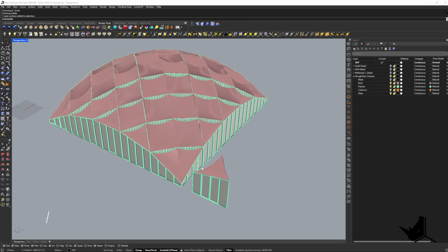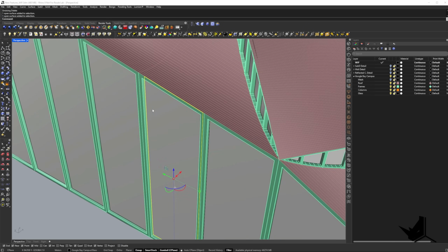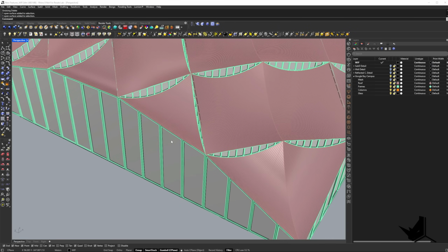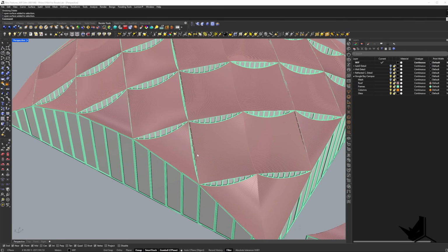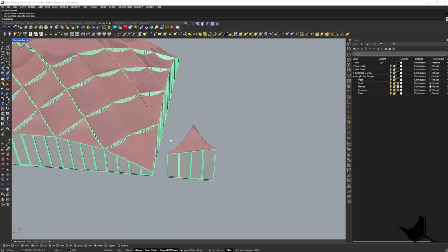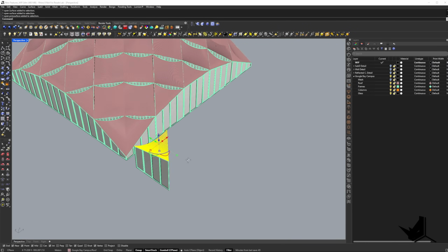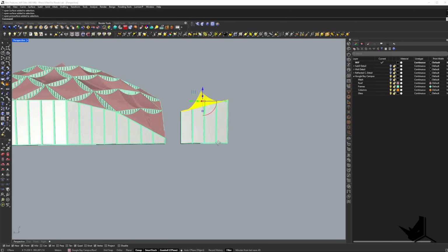As you may know, the 3D printed model has to be watertight, and this feature allows you to do just that without much hassle at all. So instead of joining all of these faces together and then trying to Boolean union the whole thing to get the STL file out, you can simply select whatever you want and create the shrink wrap around it.